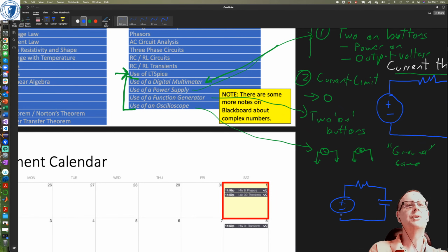But what people will do is, if they've got a circuit that they're measuring, again, let's measure the voltage across the resistor and the voltage across the capacitor. One thing they'll do, and this is to the CRO, rather the cathode ray oscilloscope it's called, or the oscilloscope, right? Let me just draw a little screen there. They'll connect one set of probes up like that, and then they'll connect the other set of probes up like this.